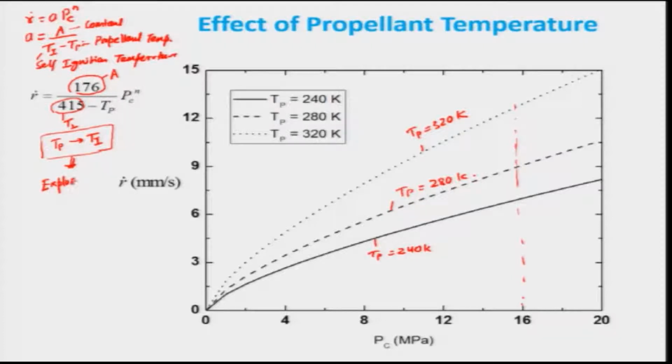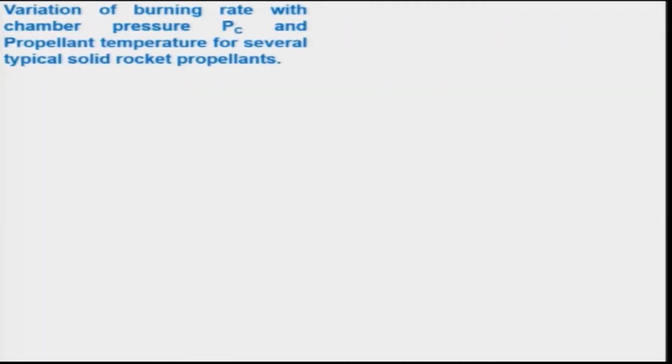That means the burning rate becomes infinity, particularly at high chamber pressure. So, therefore, one has to be very careful while designing a solid propellant by controlling its chamber pressure. We will be looking at how this burning rate is sensitive to the propellant temperature. Let us now look a little further